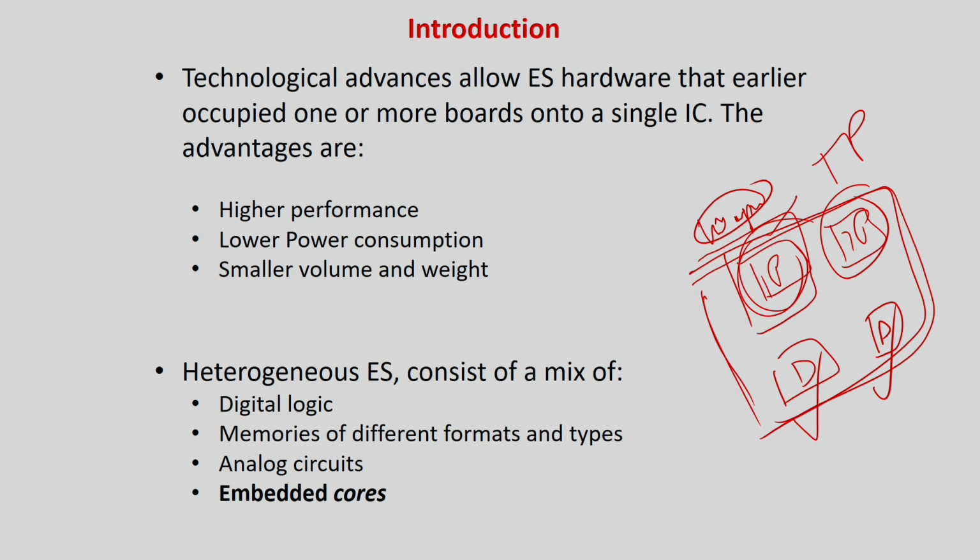If a lot of access is given to these internal IP cores... For the cores I have designed, I have full knowledge, but for the IP cores I have sold to you to be used, I don't want you to back engineer or reverse engineer them. If I give more access to the pins of the IP cores, you can do reverse engineering and try to find out my design. So they also give a wrapper kind of architecture over the IP cores, which tells you that these are the patterns to be applied, and you have to apply them through the wrapper.